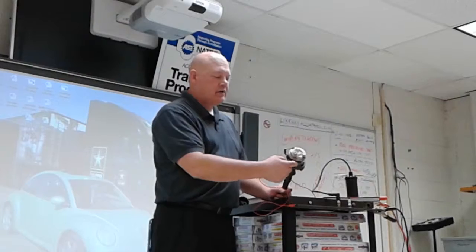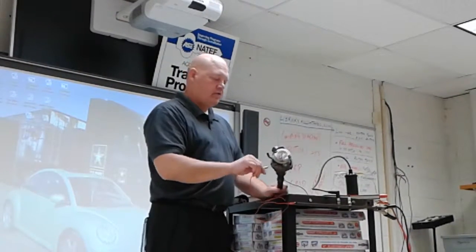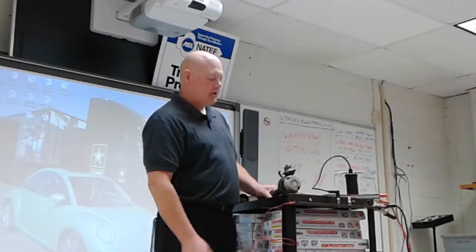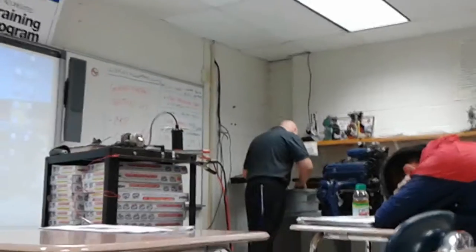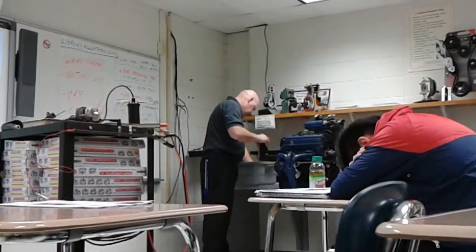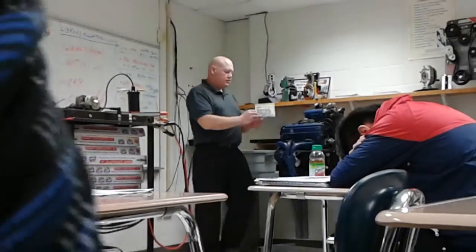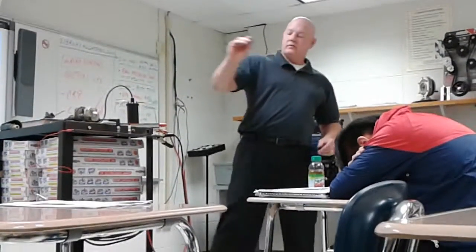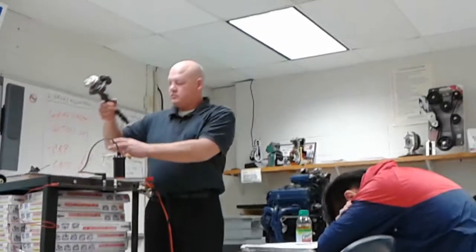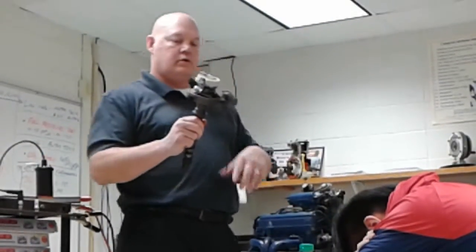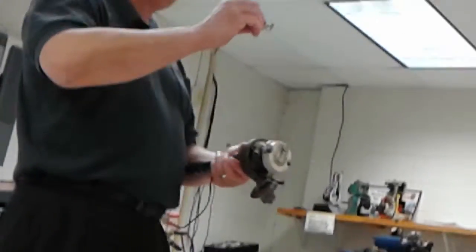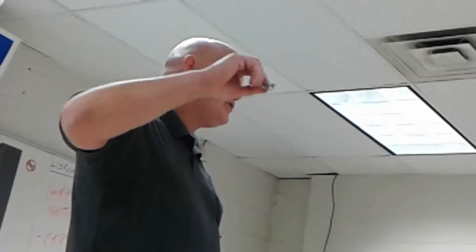This guy even has a little condenser in here. The condenser is built in for kind of a precaution, a safety device. The breaker points, let me show you some breaker points. These are breaker points. This is what is inside this little distributor gadget. That's opening and closing. Okay. Inside here are these little breaker points. Two little contacts. Current can flow through here. This is just like kind of a switch for a light.